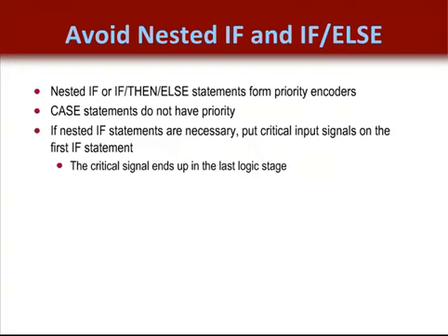If the last example was constructed with 4-input LUTs, it would require only 2 logic levels. Recall that the function had 9 inputs, which would require 2 LUTs in series and a total of 3 LUTs. So see if you can make that work and replicate what we expected and how the difference would come by using a case statement.